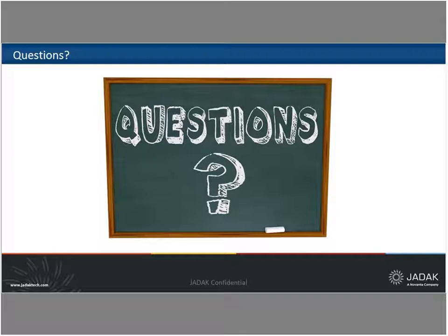Very well. Now we have two questions that are pretty technical, so hopefully I say these right. One of them is, we are interested in knowing whether country-specific registration or notification is required to place on the market medical devices that contain RFID tags. Do we have to declare use of RFID frequency in some countries? Not necessarily of the tags themselves, but you definitely do need to be aware of the RFID interrogators, the power output, and whether or not they pass the regulations for that country.